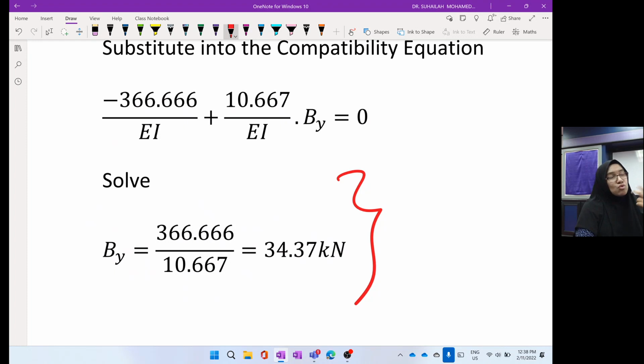We have actually two options. Either we draw the diagram, put in the value of BY and calculate the remaining using the equilibrium equation, right? And we actually have an easier step, which is to calculate the 3 remaining reactions using the principle of superposition. Remember the general equation?